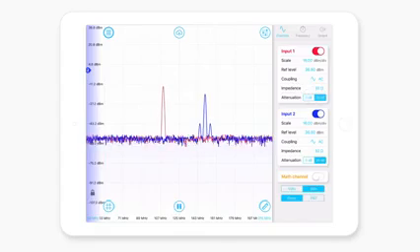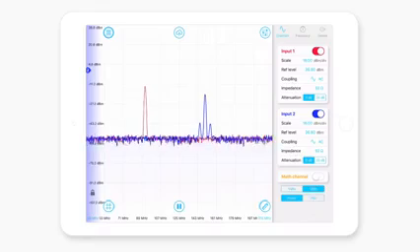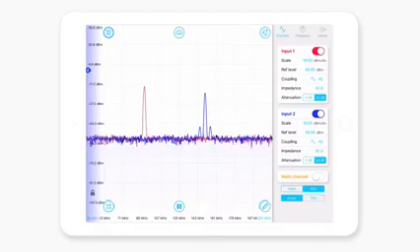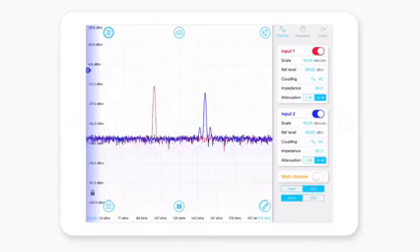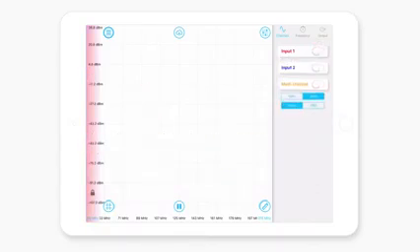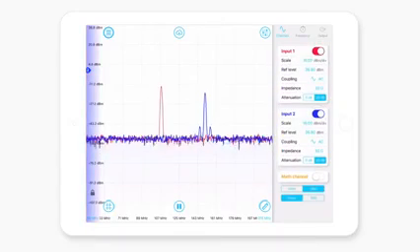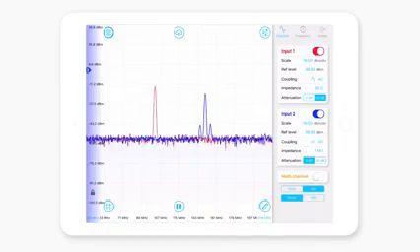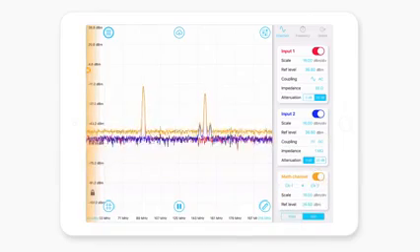You can't see it in demo mode, but generally, if you've got a very high amplitude signal, then you want to run on 20 dB attenuation to make sure that you don't saturate the input analog to digital converters. So we can turn channels off, we can turn them on just with these slide switches. We can also look at a math channel, which is kind of cool.